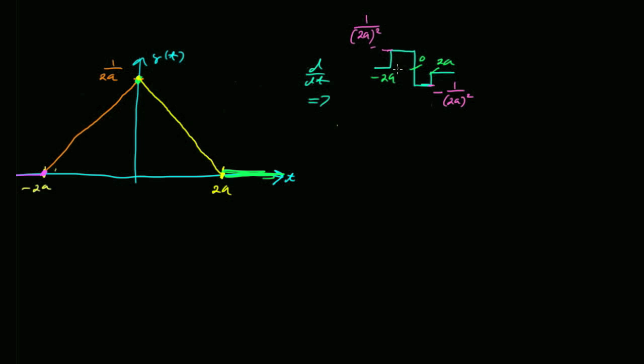So, is that right? Yeah, area of 1 over 2a. So putting it all together, it's 1 over 2a sine a omega over a omega. And then we have to shift it to the left by a units. So that's e to the j a omega. Shouldn't we make it negative? What's that? Oh, no. No, because it's shifted to the left.